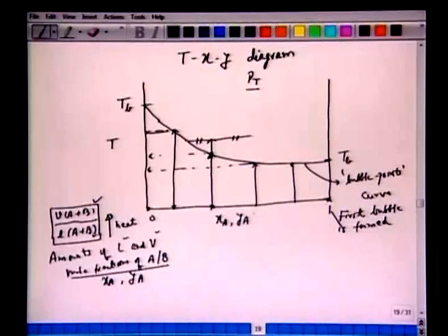One can also measure the composition of A in the vapor phase and the liquid phase. Now we have two phases here. All right, so this is a liquid. Now we have L plus V, the liquid phase and the vapor phase. If we take another mixture here, let's say we have heated here, we reach this bubble point, we further heat, then again there is phase separation.